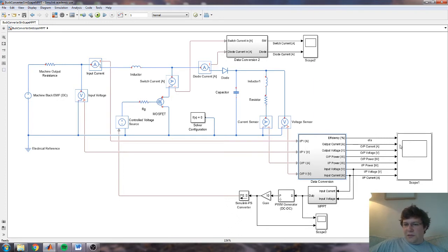And I just got a big scope so I can look at the efficiency and the currents and voltages and that sort of thing. So if I was to run this now, it shouldn't take too long to solve, it's quite simple. If I ran at higher switching frequency for the purposes of the example, and I wanted to simulate over the same amount of time, which is a second, it would take a lot longer to simulate. So that's my other excuse. We'll also have a little look at the per cycle waveforms as well. So just crunching the numbers, and the old fan on the computer is... oh, that may have been loud.